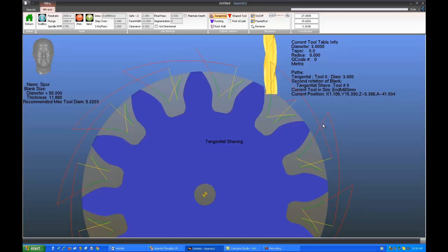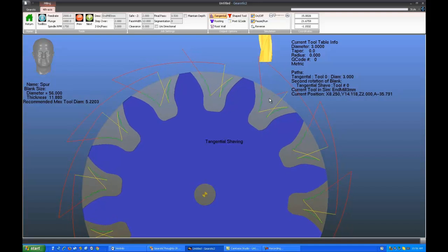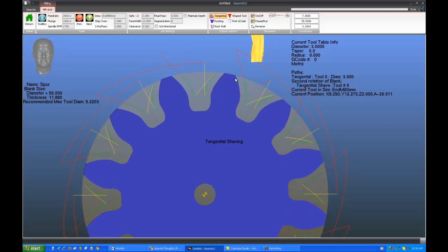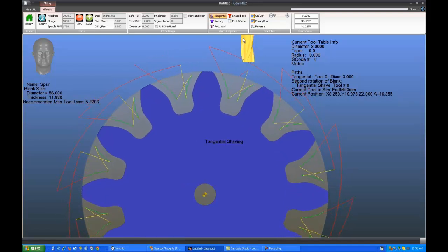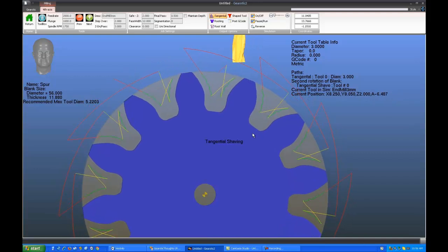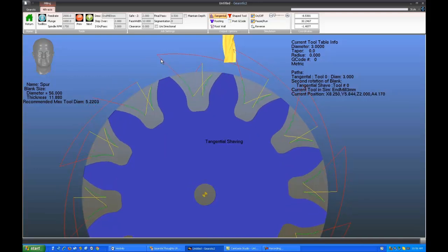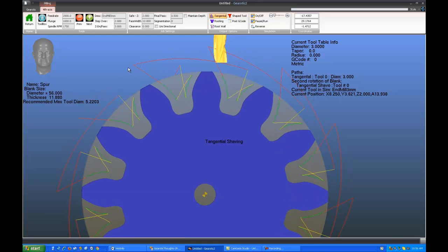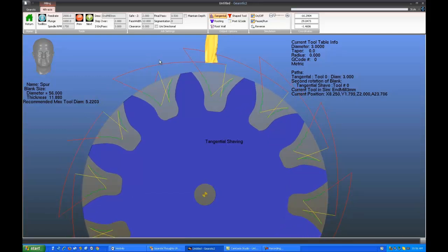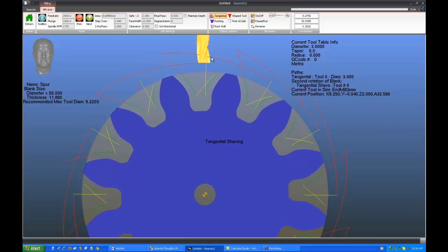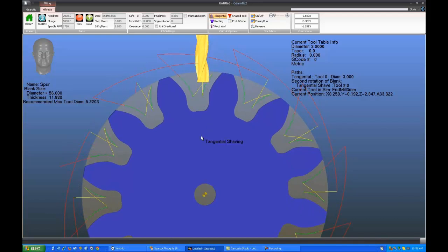And you can see the gear is rotating until its involute curve is at 90 degrees to the tool, which means that the edge of the gear is being shaved on the tool in order to create our waveform. And this is why our tool paths have looked so strange all this time: these red rapids, for example, are being shown in their actual trajectory as the A-axis rotates.